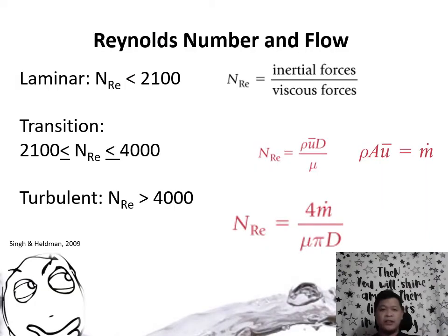Technically, the Reynolds number is the ratio of the inertial versus the viscous forces. And it's categorized as either laminar at less than 2100, yung compute niya na value, transitory or transition flow if it's between 2100 and 4000, and turbulent flow if greater than 4000. Ano bang importance ito? Depending on whether the Reynolds number is laminar or turbulent, nagbabago yung ibang equations or yung pagtrato natin sa isang fluid flow system. So, yun lang naman yung importance nun. And of course, it gives us an idea ano yung itsura ng flow niya.